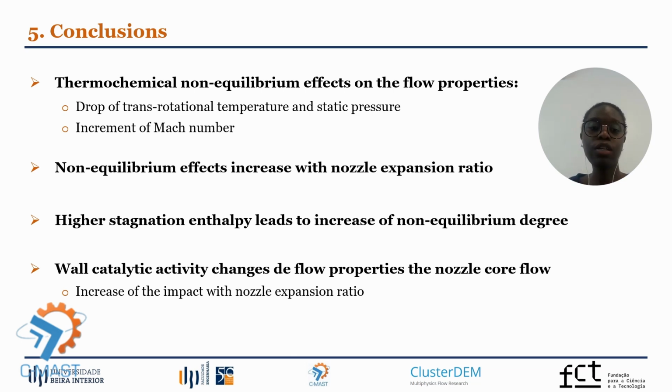We also found that the catalytic activity at the surface of the nozzles will change the flow properties at the nozzle core flow and also at the test chamber, and this impact will be intensified for higher expansion ratios.